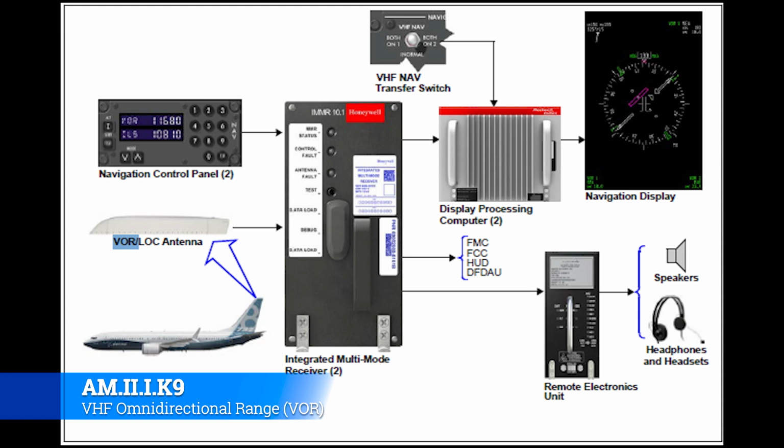And then that navigation display, we're going to look at here again in just a second. It's the same information that was on the VOR instrument display that we looked at earlier. It's just been digitized, so let's look at that a little bit more deeply. And the FCC is the flight control computer, a brain fart on my part. It basically will tell you, hey, this is the position the flight controls are at based on these inputs and these conditions. We need to do certain things, and we'll get into that a lot more when we get to flight controls. So sorry, just blanked on that one.